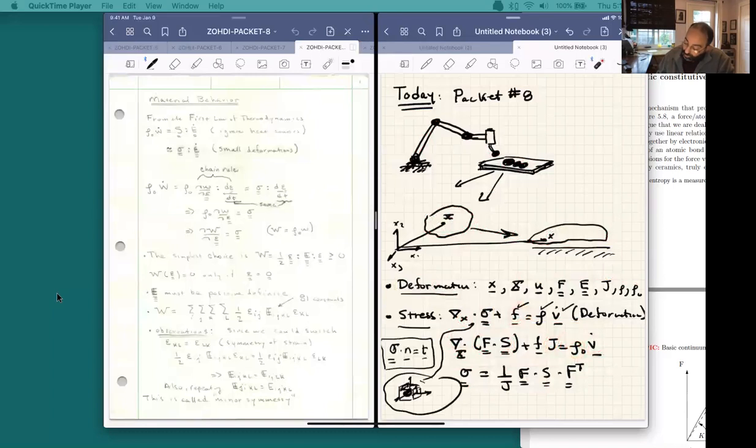So there's pluses and minuses. This, of course, is posed over the reference configuration. This is posed over the deformed configuration. Depending upon what we know from one state or the other, you should feel comfortable with utilizing either or both of these formulations and understanding where they came from, where they're applied to, and then depending upon the simplifications that one might have, you'll get different formulations and you might find it more advantageous to use one formulation or the other.